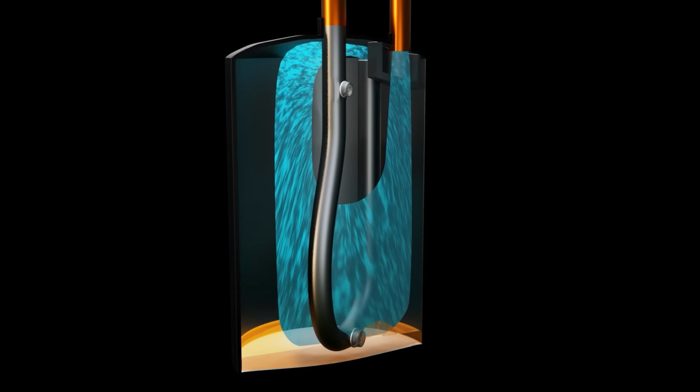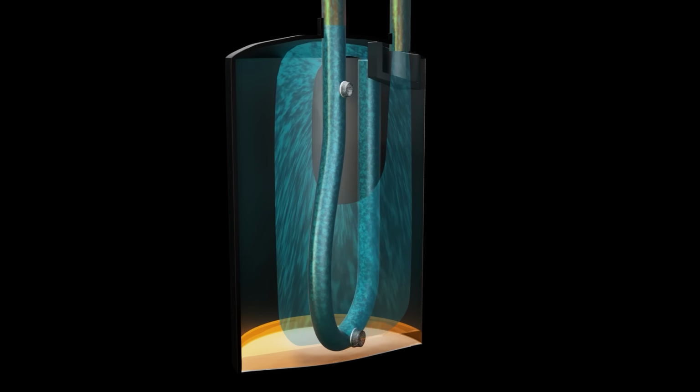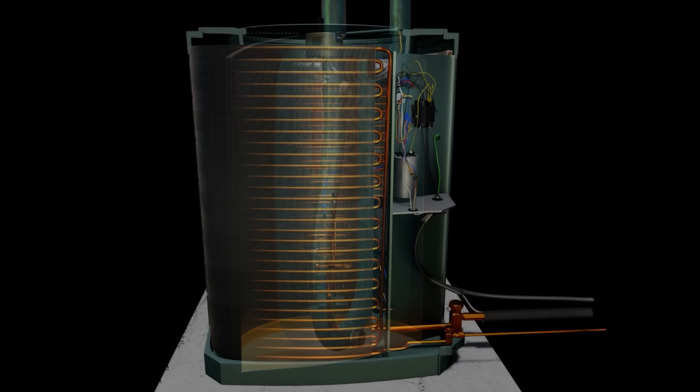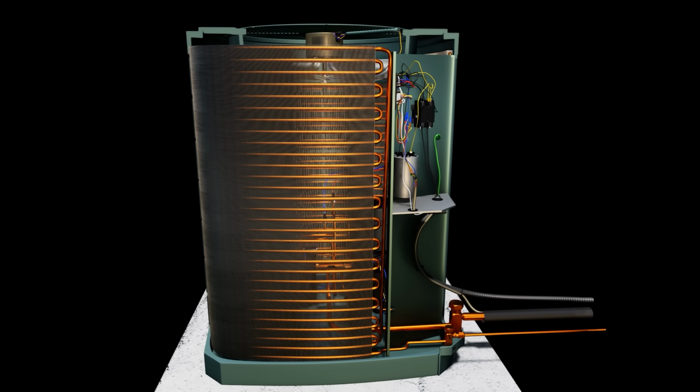And as you can see, the way it works is the vapor refrigerant drops down into the bottom of the accumulator along with the oil. There's a little pickup port at the bottom that allows the oil to be drawn back to the compressor, as well as a little bit of liquid refrigerant, but it controls it enough so that it's not going to damage the compressor. So you could have a good amount of liquid inside that accumulator and still prevent slugging or flooding of the compressor, which is when we get a lot of liquid refrigerant back to the compressor, which is an undesired situation. But we still have that little pickup port, which allows us to bring oil back to the compressor.